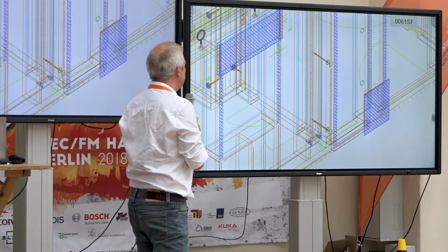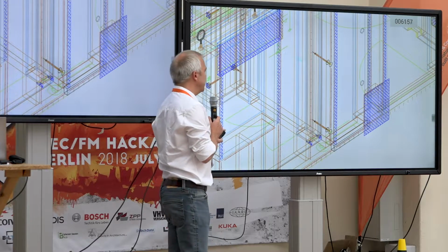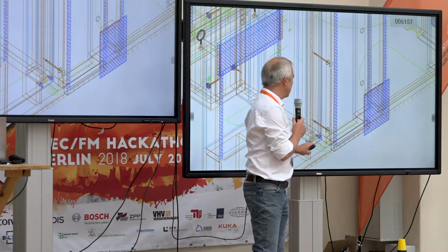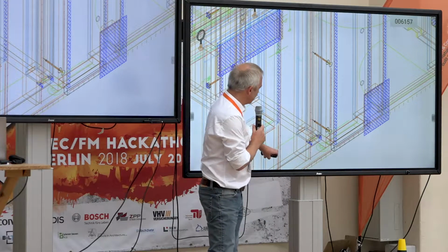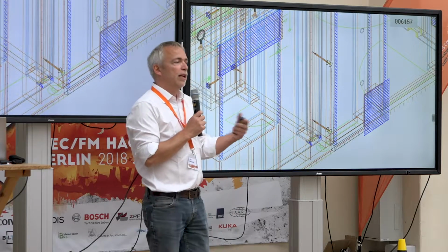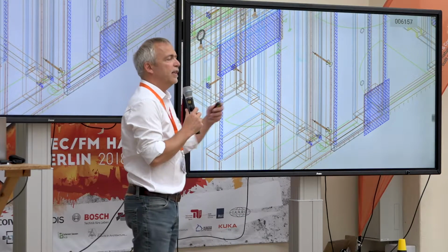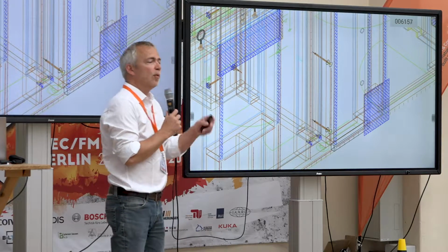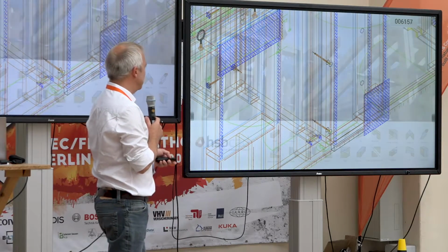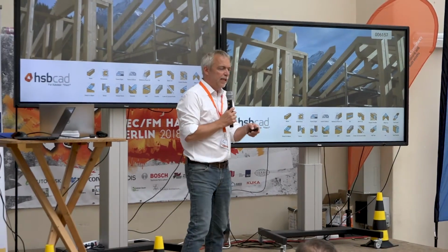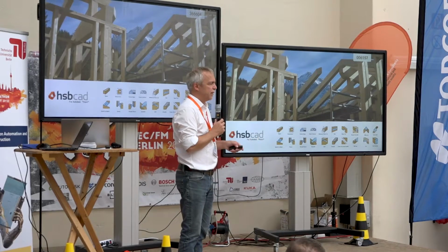So as I said, in the drawing you have to specify lots of things. Obviously millings and operations like that. Cutouts, obviously, you see these dotted lines here, they are nail lines with nail spacings. They are generated either automatically, wherever possible. Then there's possibly some validations that run, or manual adjustments. And on top of that, the validations of these manual operations. We have a plugin in ACA, a plugin in Revit, as I said.